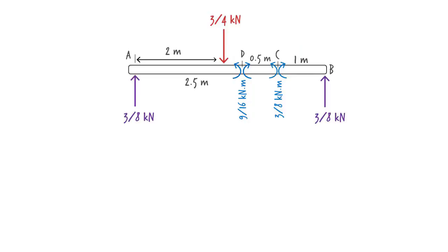In addition to bending moment, beams carry another internal force. We call it the shear force. It is a force parallel to the cross-section of the beam. To see why shear develops in a typical beam, consider segment CD.